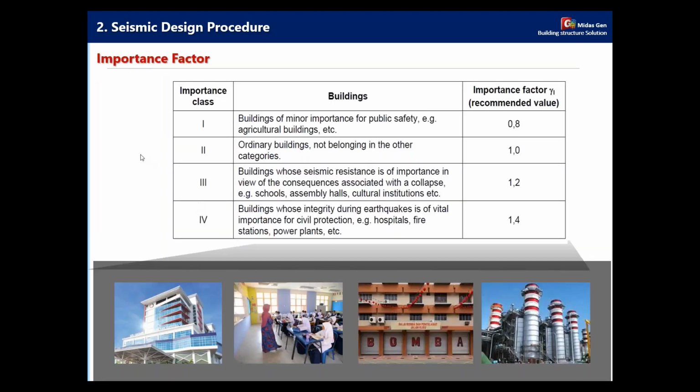The other important factor to know about is the importance factor, and this factor helps us to assess the protection level of the building against the seismic action. Some buildings, when we are erecting them, we can assume that they are very important, depending on the number of people that are going to use the building, and depending on the material and the equipment that we are going to put in the building.